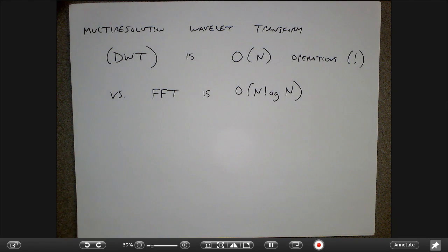But if I want to understand and design a system, right? So when we design filters and stuff like that, all of that is inherently a frequency domain concept, right? We want to know, how does a filter shape the frequencies of the incoming signal? And that's something that we really can't talk about with wavelets. That's a frequency domain kind of concept. So it's kind of a situational thing about when you want to use different things.